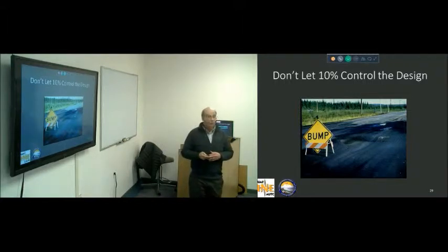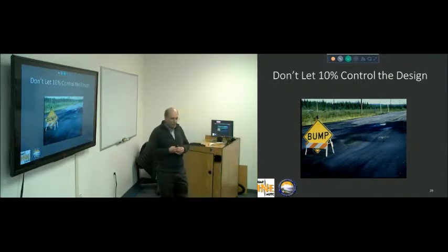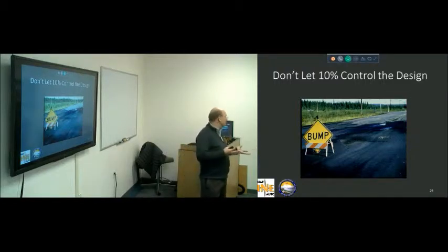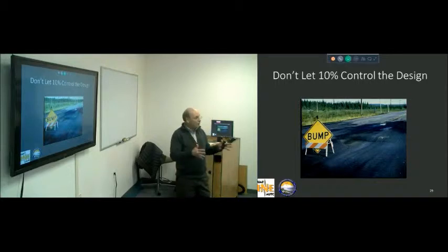So one of the ways to do this is break your project up into segments that are uniform and design for each one of those on their own merits, and try to work with that. Of course, you do have to pay attention to the constructability issue. As we did one time, we were breaking it up in 100-foot chunks, and that cost us a tremendous amount of money because the contractor was changing, going in and doing a 100-foot chunk.